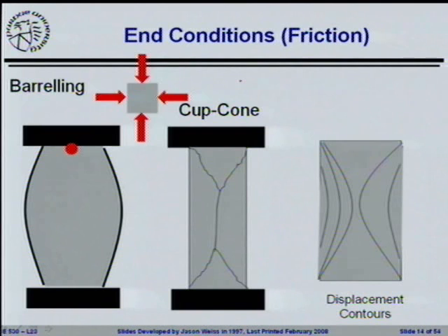And the big issue here is the idea of end restraint. If you have platens on your machine, so you can picture this as the big steel platen, you've got a hydraulic cylinder that's pushing down, you've got something that's pushing up, and this is your concrete. If you don't do anything, you will have friction at the end of your concrete cylinder that keeps that edge from expanding.